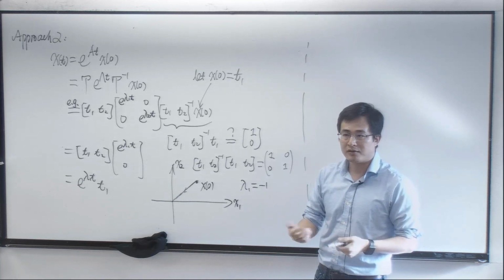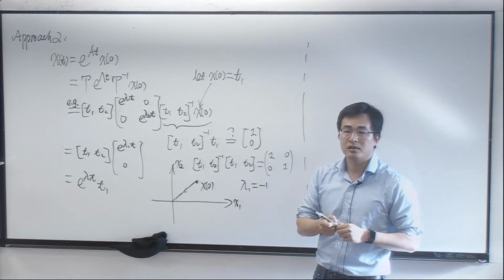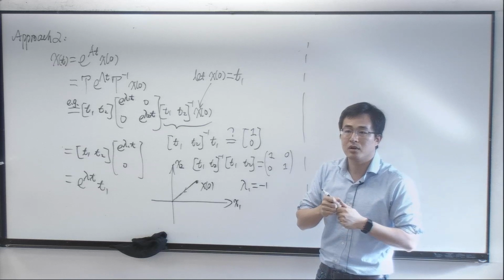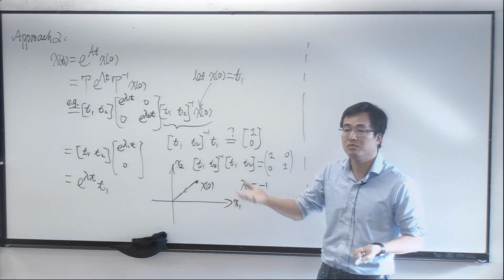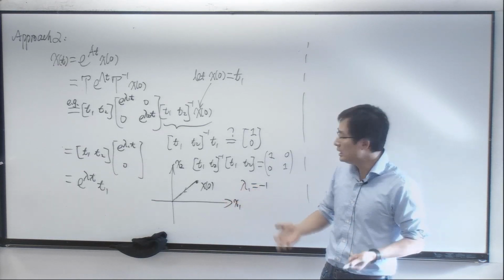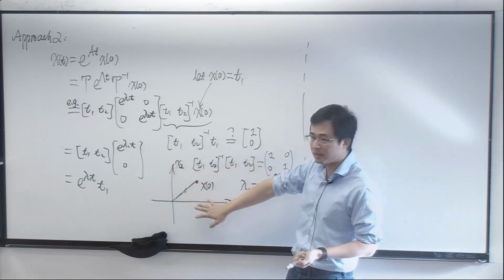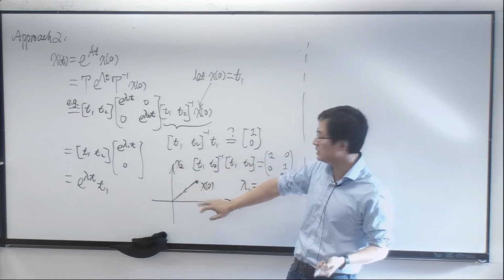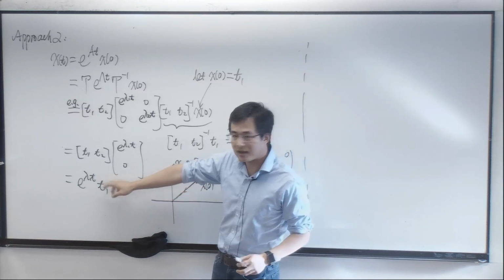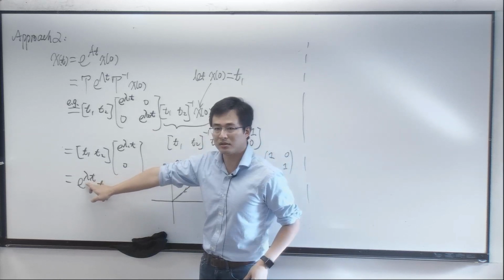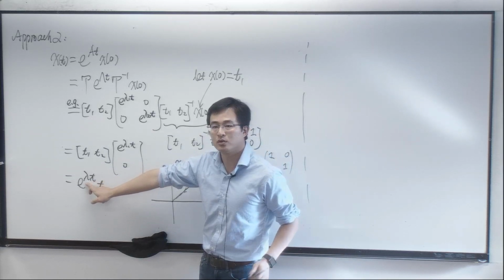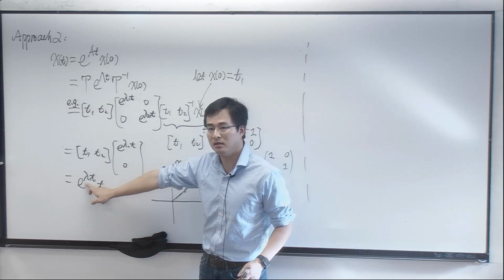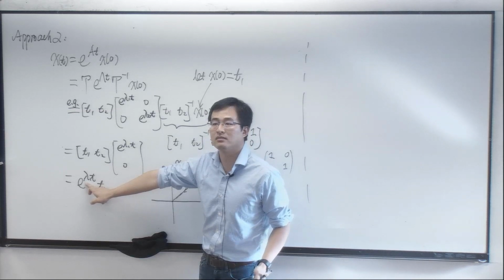The poles of the ordinary differential equation, the roots of the characteristic equation, are going to show up in these modes, right? So this is exactly a similar concept. Actually, I'm going to talk about this a little bit more. So you already see the fact that eigenvalues of a matrix relate to poles of the system, right?